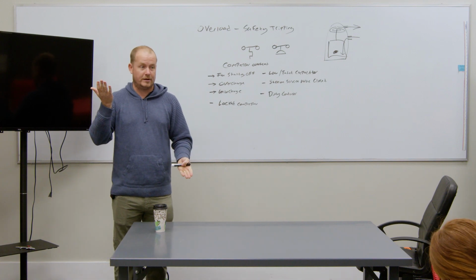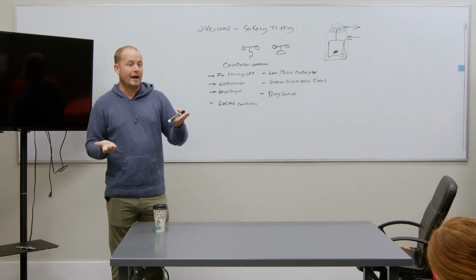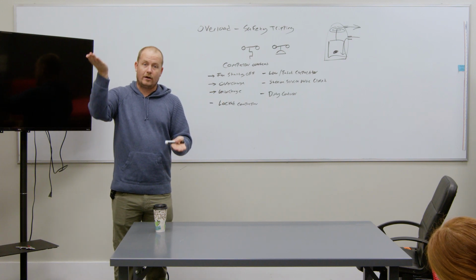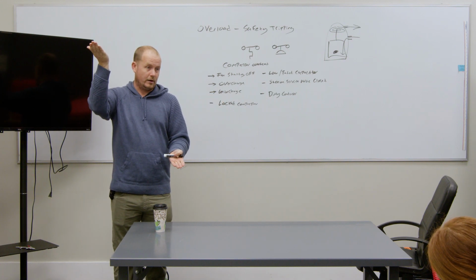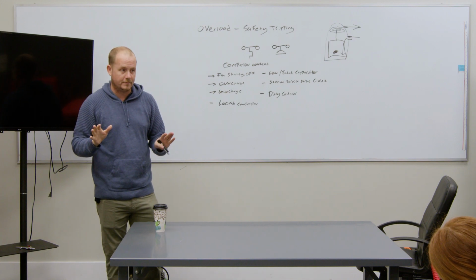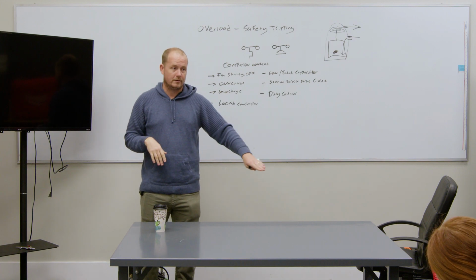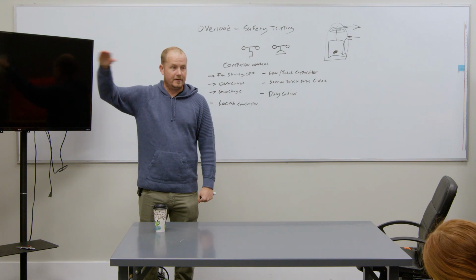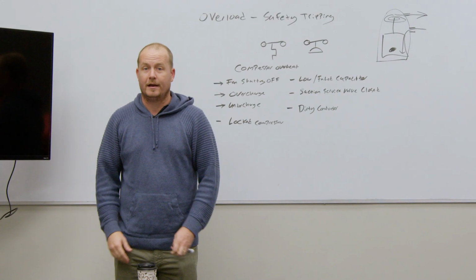That means you don't have as many molecules moving through that compressor, and that's going to result in high temperature. Also, high compression ratio. So if you have low suction pressure and high head pressure, that also causes a compressor to run hot. So if you think of it in very simple terms, when you have low suction pressure, that causes a compressor to run hot, and when you have high head pressure, that causes a compressor to run hot.